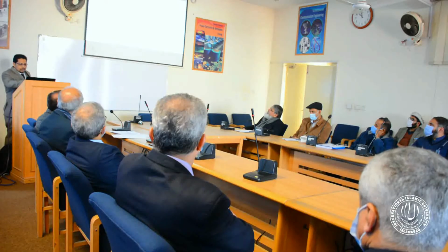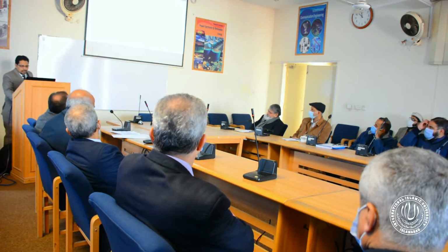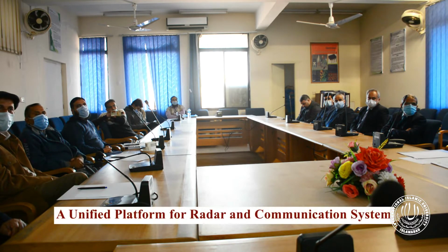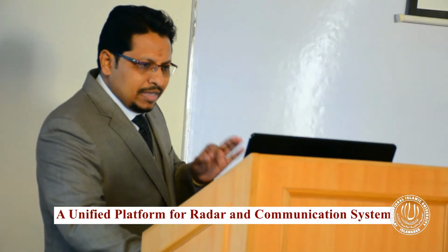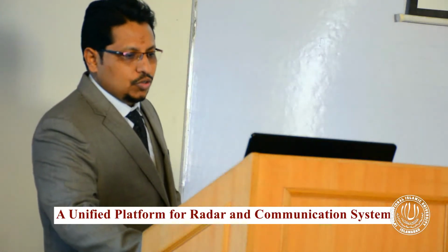So we calculate the range. We take the phase difference between the two above components of F1 and F2. Then from this equation we can easily get the range based on the phase difference of the frequencies. And it's clear from the above equation that the phase difference can be used to measure the range of the targets. So for radar unambiguous range, we just keep delta phi equal to pi, so that we get the system's maximum unambiguous range. Moreover, if the difference between the two frequencies is large, this will lead to better range accuracy due to the proportionality to delta F.